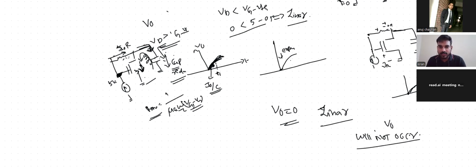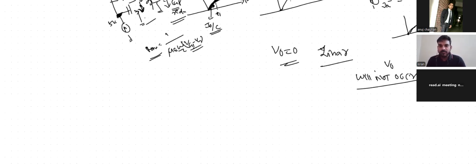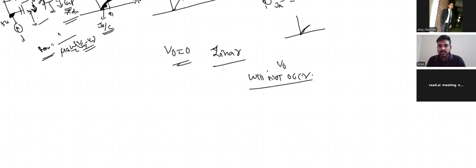What I will explain here is that this resistor always takes a 5-volt drop, because it is carrying the 5 milliamperes continuously. So the gate-to-drain voltage of the transistor, VGD, is always 5 volts, which is always greater than the threshold.